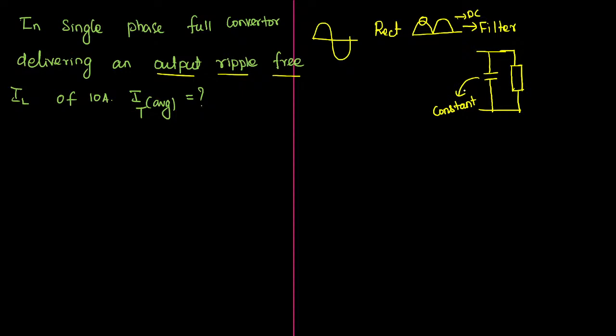this capacitor will be constant as long as you are not allowing the capacitor to get discharged. So the conclusion is, it will be acting as a constant source with a positive and a negative polarity, because in this direction only we have charged the capacitor. See there, if the capacitor is connected in parallel with the load, it doesn't matter whether we are sending a pulsating waveform from the input or not.